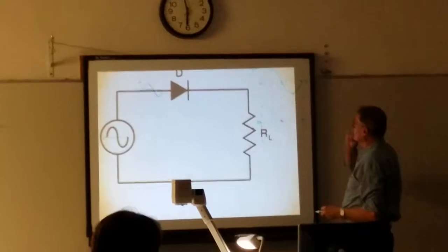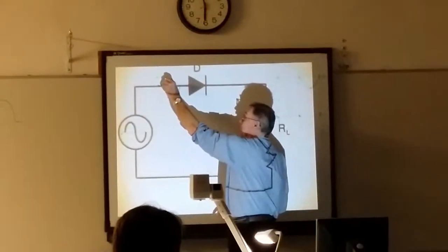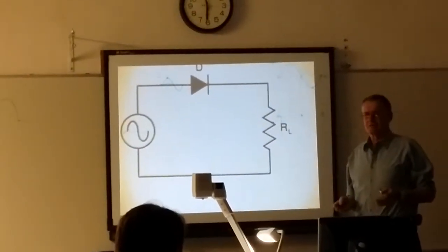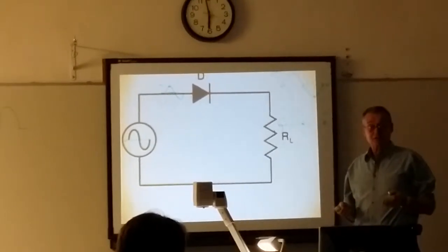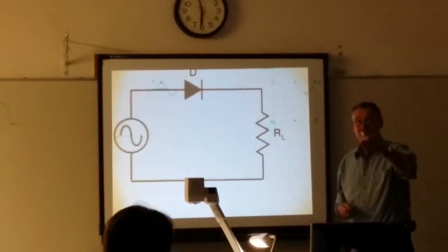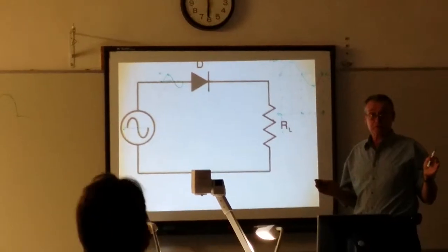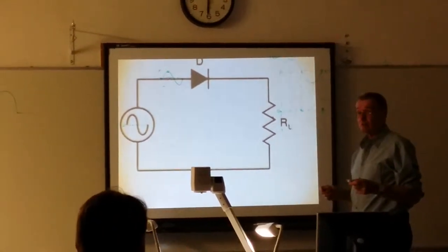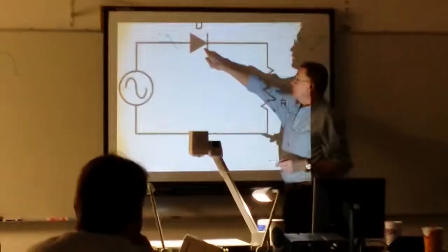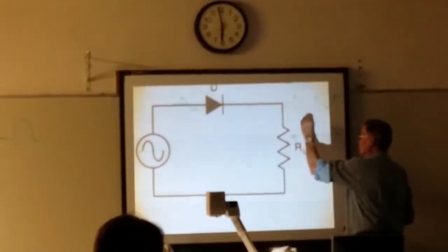When that's positive, is the diode on or off? That's at this time right here, at 10 volts. How's the diode going to respond to that? Since the plus 10 is connected to the anode, the diode is on. And when it's on, it's a direct short. It's a switch. Remember, a diode's an electronic switch. You okay with that? I'm okay with that part of it. So when it's on, that's a direct short, and that voltage is going to appear on the output, isn't it?